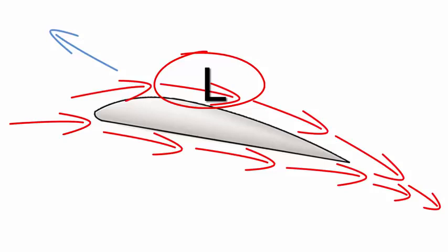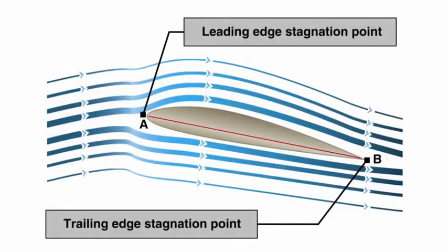Because of the manner in which air flows underneath the airfoil, a positive or high pressure results. At a point close to the leading edge, the airflow is virtually stopped at a stagnation point, and then gradually increases speed as it moves further aft. At some point near the trailing edge, the airflow again reaches a velocity equal to the flow on the upper